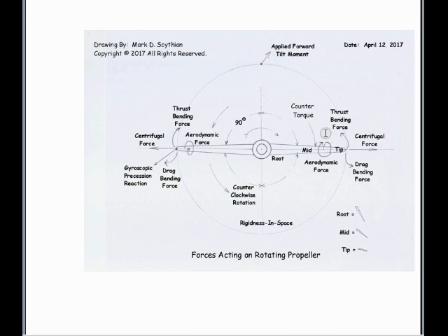But let's say this is a single propeller, and let's say it's flying level on an airplane, we're facing the airplane, and let's say the pilot put a right input in. This would be the same as tilting this propeller disc to the left, and since it's rotating counterclockwise, you'd actually get a moment backwards, which is represented by negative pitch if this was an airplane looking at it forward.